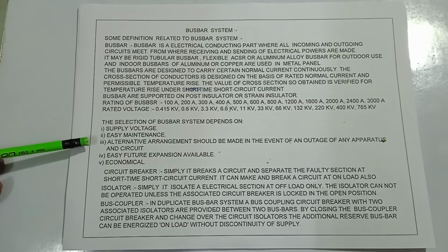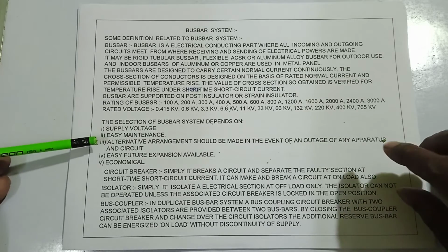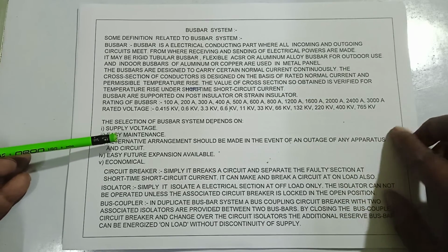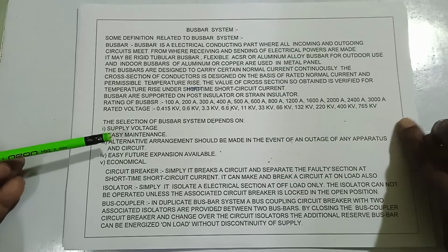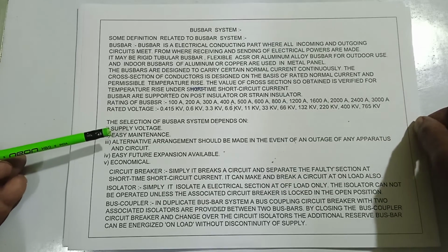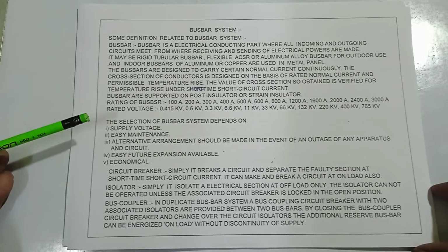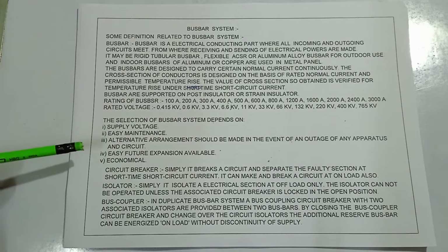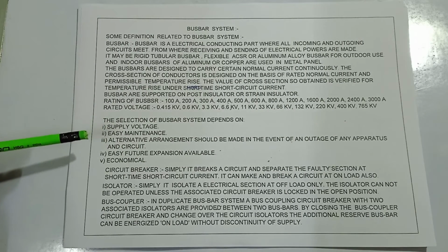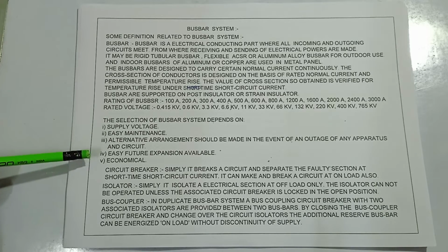The selection of busbar system depends on supply voltage and easy maintenance. Alternative arrangement should be made in the event of an outage of any apparatus and circuit. Easy future expansion should be available, and it should be economical.